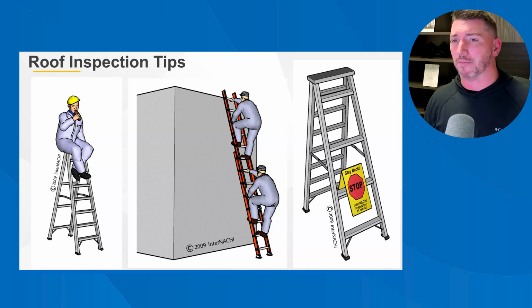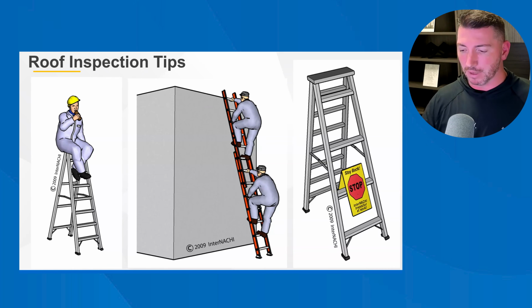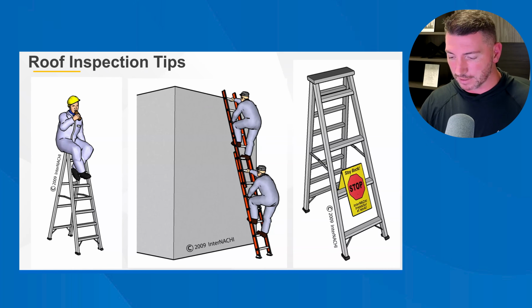So if you're looking at a pipe boot that's very old and it's a 20-year roof and it seems like that pipe boot is from the original roof install, that could potentially be a problem in short order if it's not already.